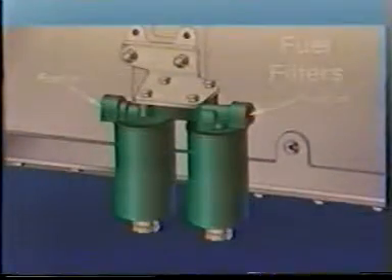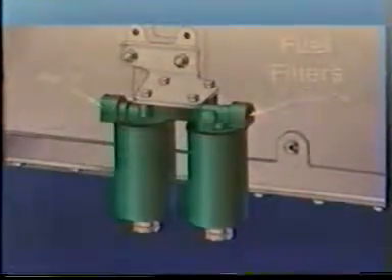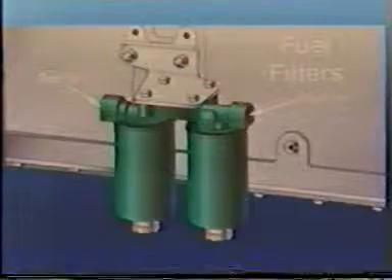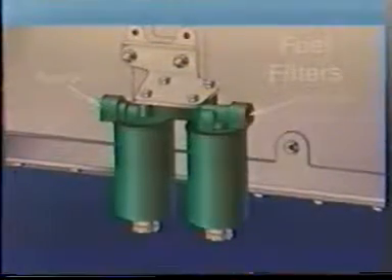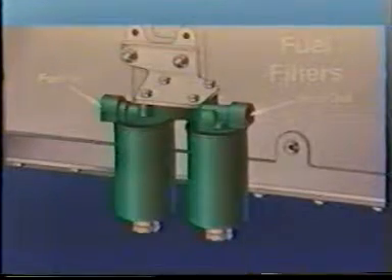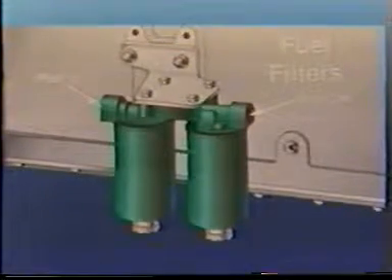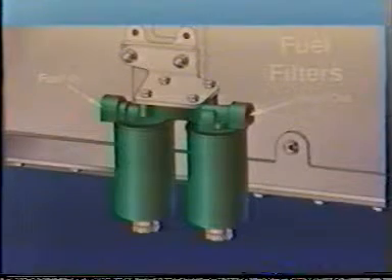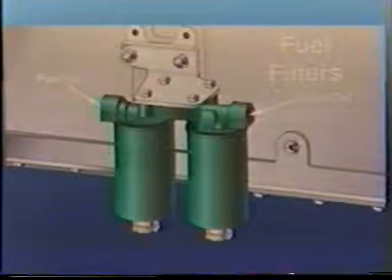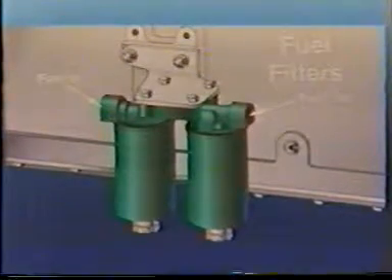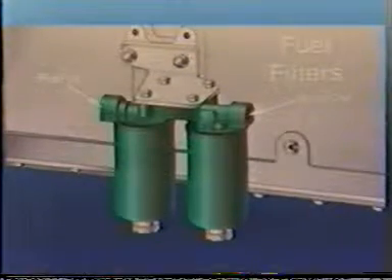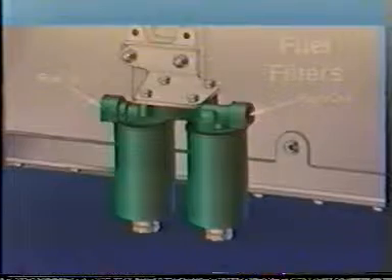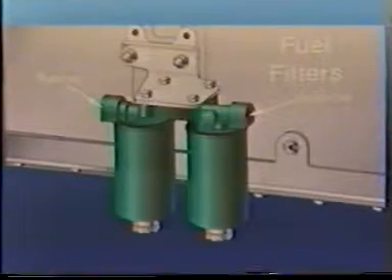Fuel flow from the supply tank is directed to the dual fuel filter head. The fuel filters have water separators and elements that filter down to 10 microns. Water separator elements are mandatory as the actuators in the control valve body are sensitive to water. The maximum inlet restriction at the filters is 4 inches of mercury with a clean filter and 8 inches of mercury with a dirty filter.